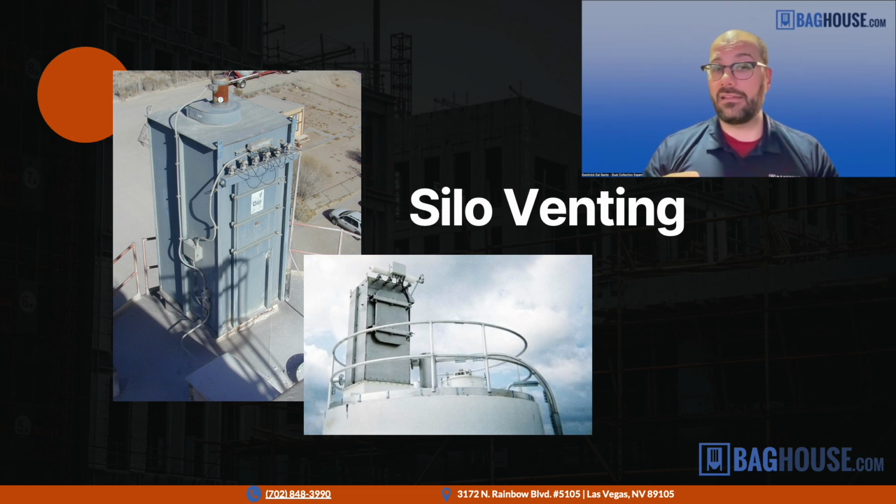Sometimes they have a fan that helps pull the air through. Sometimes they don't have any fan. So only the air being pushed in is what goes out through the bin vent. Other times it's both things. The air is being pushed in as well as the bin vent has a fan pulling out. But in either setup, it essentially works the same way as your normal baghouses.